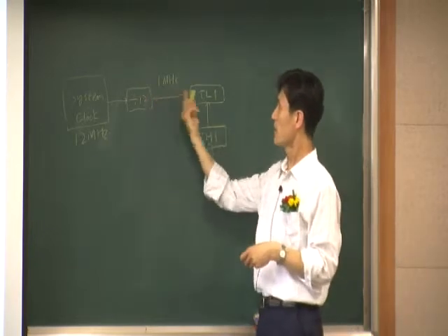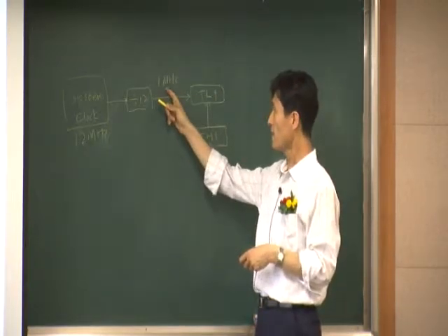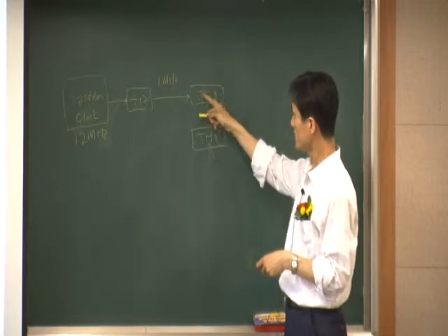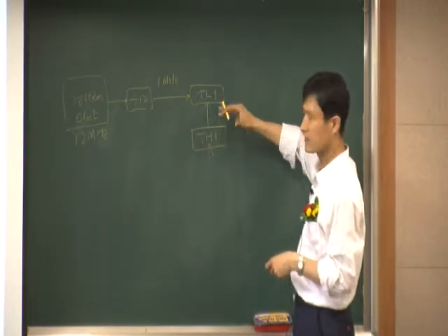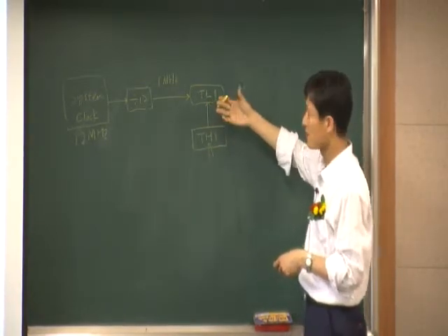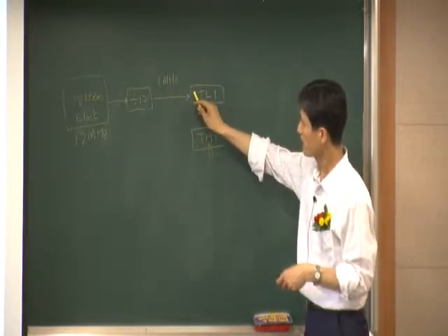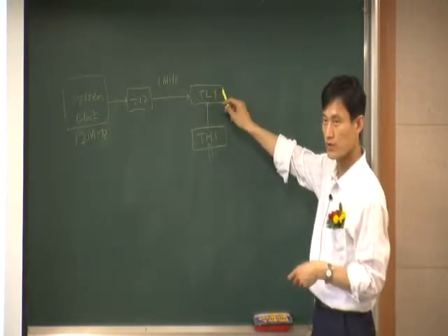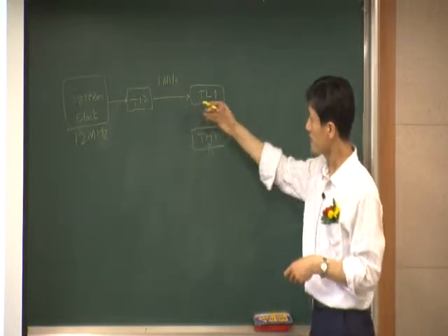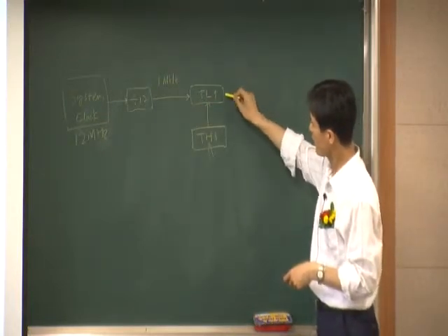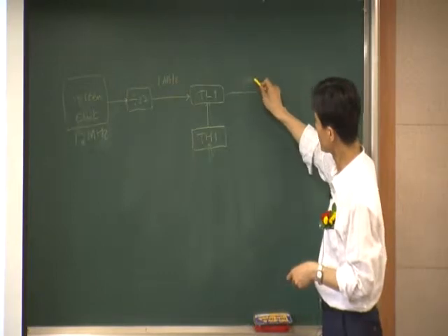And every time you get a 1 megahertz clock, the value inside here is incremented like a counter. And this is 8 bits, right? So you have 1111 1111, and then the next clock comes in, it becomes 0, and you have a timer overflow.